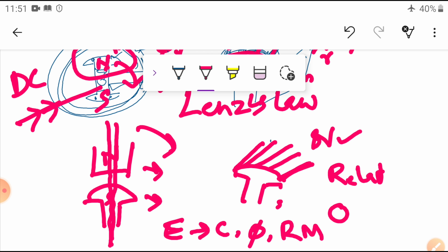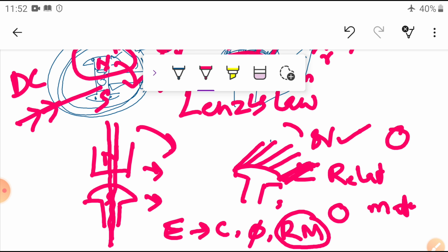But in this case, a conductor is present and a magnetic field is present, but there is no relative motion, because the relative motion between the rotating magnetic field of the stator and the damper windings in the rotor is zero. Then no EMF is induced in them. These copper conductors act as simple material, not inducing any EMF and not opposing anything. They only work initially, when required to start the motor. So this is the starting of a synchronous motor with the help of different methods, by mechanical means and by damper windings.